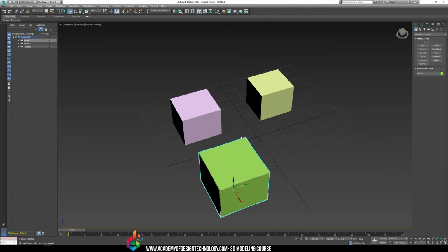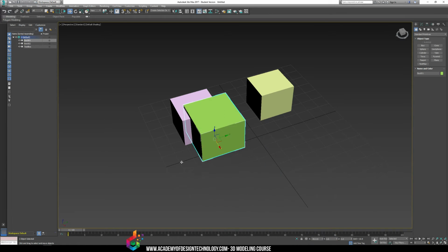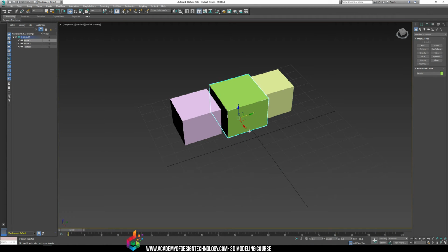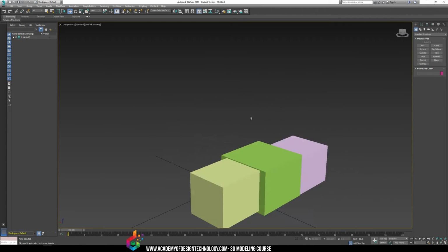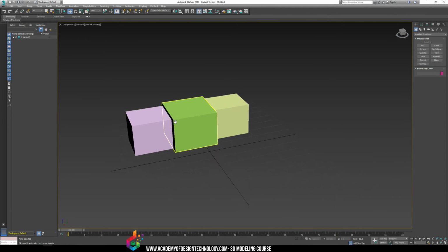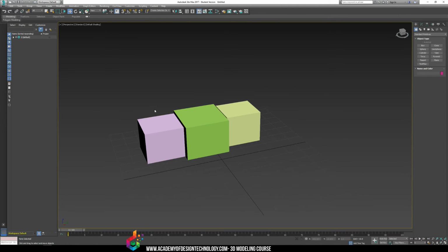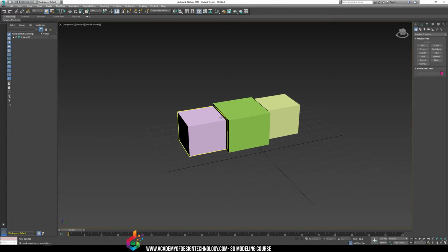And then I'll take this box that I created here, move it over here. Now I've got my 3 boxes. So practice moving the boxes around a little bit with the move tool. Remember to push Q to go to select mode, to select the box, then W to access the move tool. Now, even if you don't have Q active, let's say W is active, so you can see that select object mode isn't on, but the move tool is on, you can still select the other object.